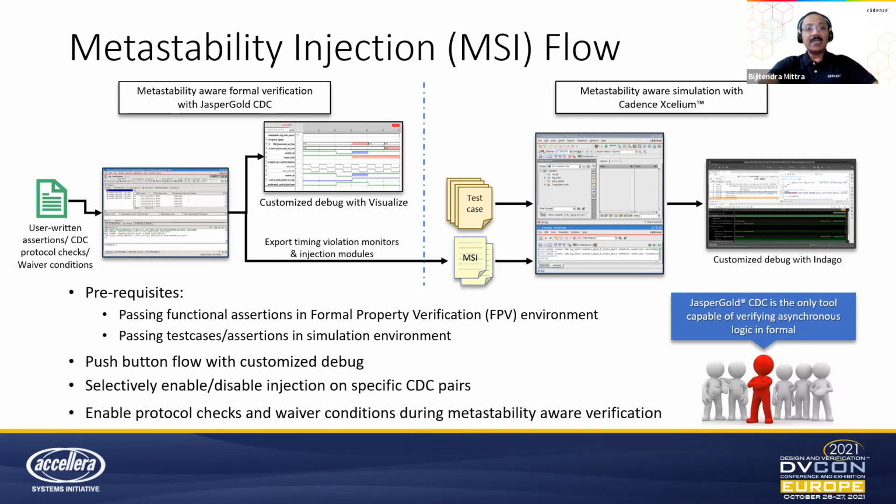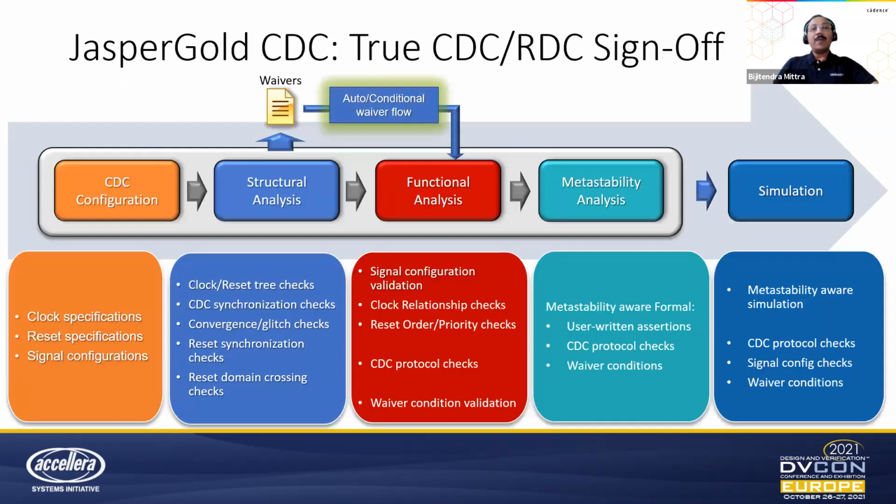At the same time, as I mentioned, in both formal and simulation, you can enable the protocol checks and waiver conditions during the metastability injection flow. Now, coming back to the true CDC RDC sign-off with JasperGold, how would it look?